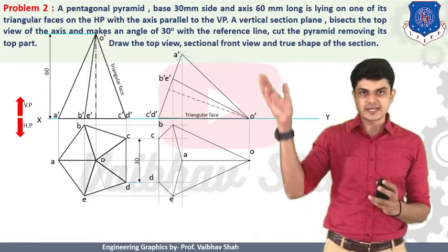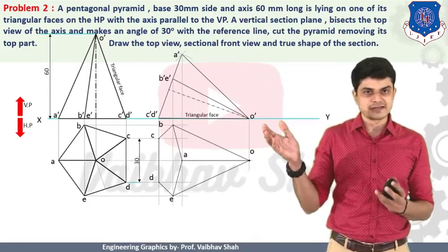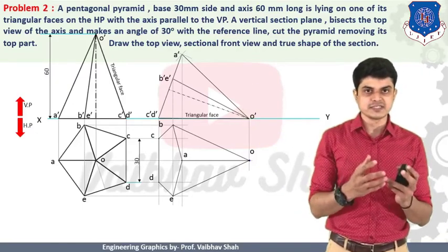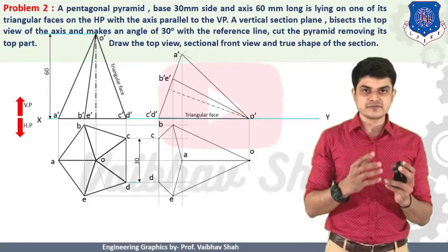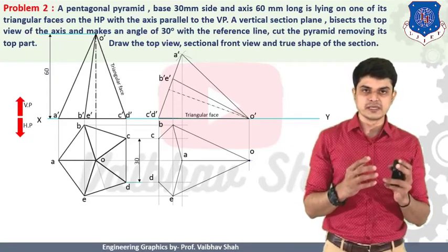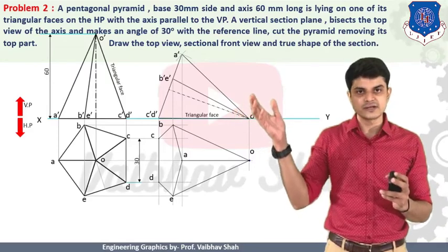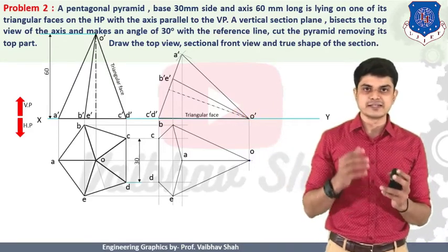When we try to take the top view, it is obvious that O dash point is clearly seen, and the base is completely seen. So each of the points of the base is completely seen, but there is one surface which is hidden from your observer, which would be your triangle face itself, O dash C dash T dash, because it comes under your object, so it can't be seen by taking its top view.